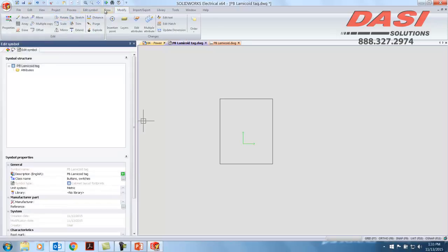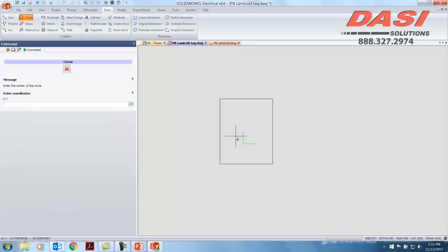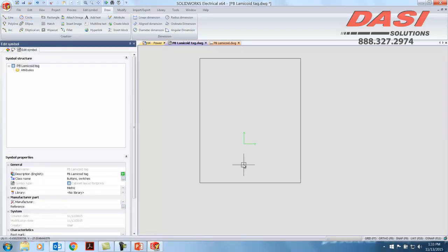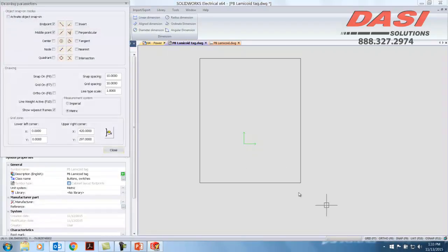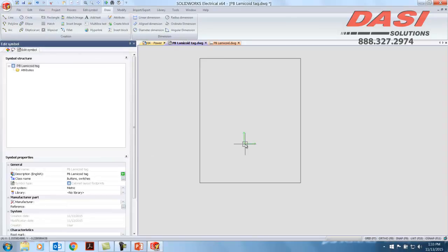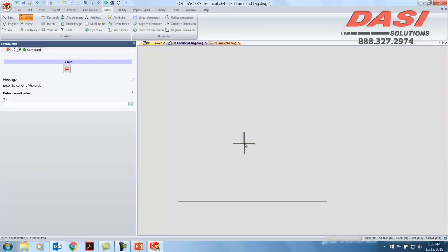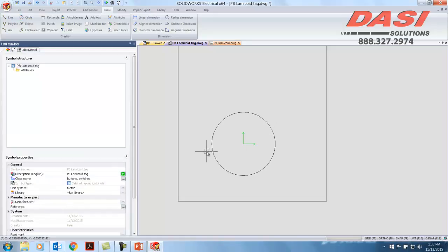So we'll just go ahead and use that. We'll use the draw tool to grab a circle just to show where that is being snapped. I normally like to use my O-snap here. Turn on my O-snap for that intersection and the origin. Close that. And so we'll go ahead and draw that circle from 0, 0. We'll say that should look pretty good.